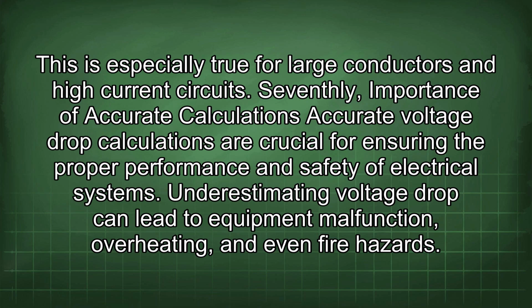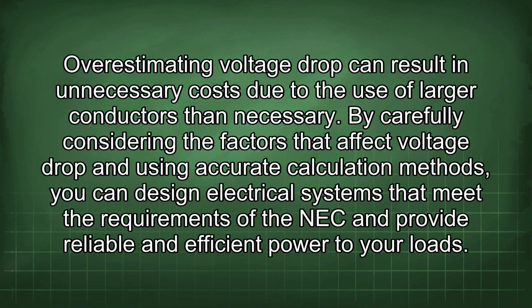Accurate voltage drop calculations are crucial for ensuring the proper performance and safety of electrical systems. Underestimating voltage drop can lead to equipment malfunction, overheating, and even fire hazards. Overestimating voltage drop can result in unnecessary costs due to the use of larger conductors than necessary.